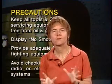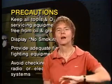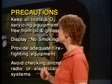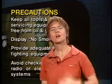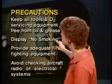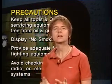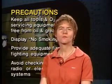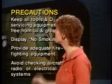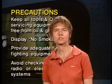Oxygen is very flammable, and you can get spontaneous combustion if anything with oil or grease on it is around the oxygen system when you're working on it. You want to display no smoking placards when you're working on the oxygen system because, again, oxygen is extremely flammable. Because of that, make sure to provide adequate firefighting equipment in the area when you're working on an oxygen system.